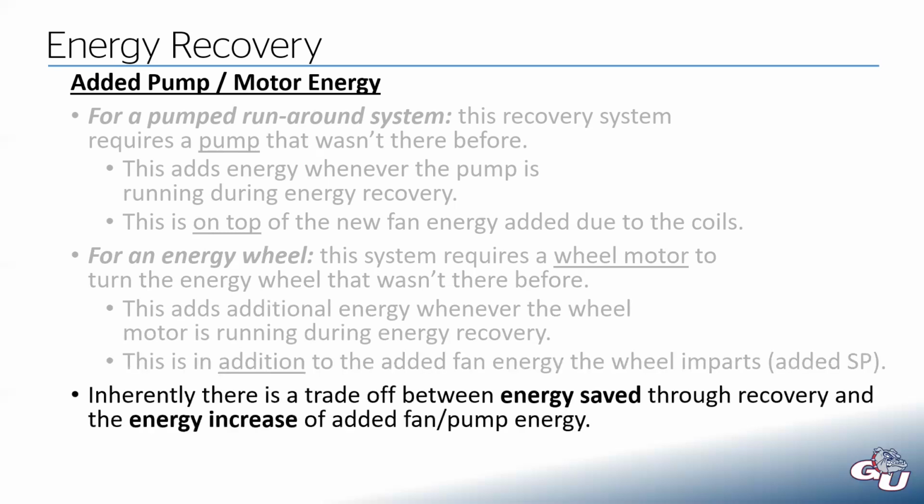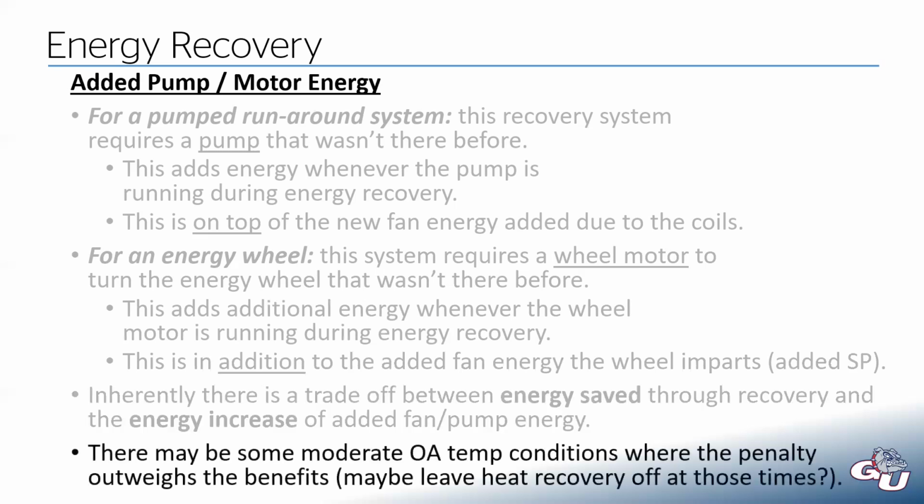So inherently, with any energy recovery system, there's a trade-off between the energy you're going to save through your recovery and some energy increase due to added fan or pump energy. There's going to be a trade-off. Energy saved plus a little bit of a hit. And there might be some conditions, some moderate temperature conditions, where that penalty you're paying to run that pump or to run air through that coil is going to outweigh whatever benefits you might see.